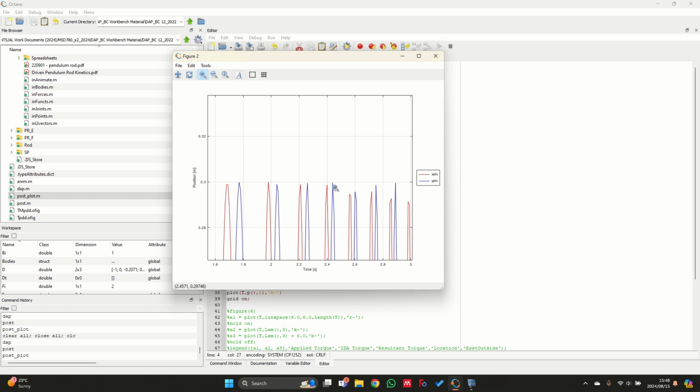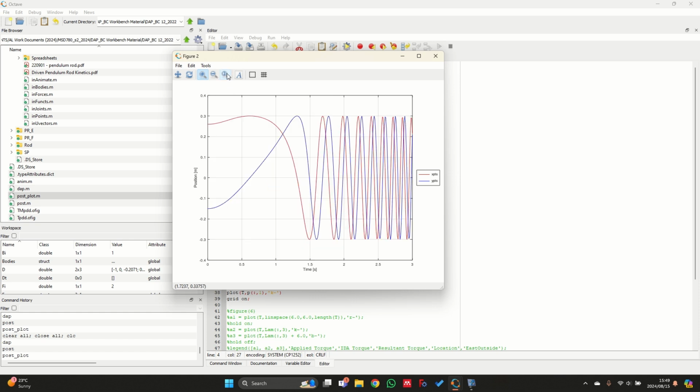If this is something that bothers you, you can once again change the reporting time step to something smaller. However, there is also a fine line between going too fine with your reporting time step. In other words, the accuracy and the computational efficiency as well.